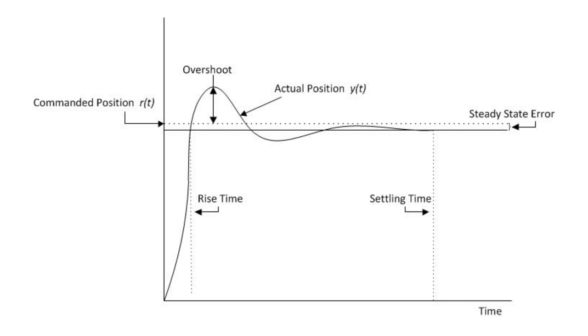We also want to get the best possible bandwidth, which means the fastest possible response, without destabilizing the system. This is done by setting Kp as high as possible without producing too much oscillation. Lastly, we want to eliminate quantization noise by having an optimal value of Kp and Kd. Quantization noise can appear in the system when these gain values are too high.